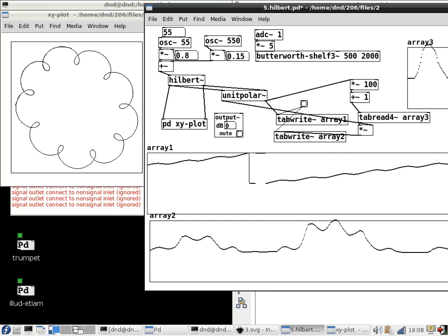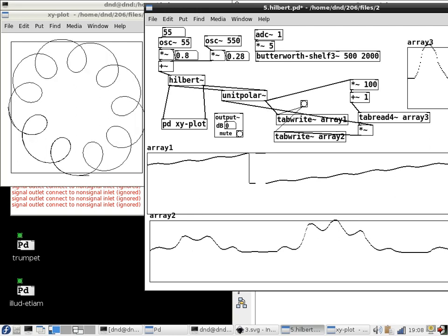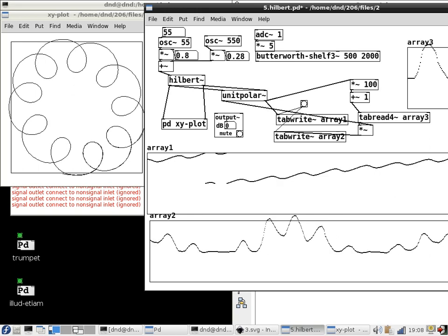But that's not going to matter because this table read, it doesn't because I didn't draw it well, but this thing, if it's an actual periodic function, will give you the same thing down here as it does up there anyway. And so this jump and these 2 other jumps don't matter. Those are inaudible when you've replaced it with a proper waveform. And now the amplitude of the other harmonic then becomes the amount of distortion that you get in this thing, which also becomes the amount of phase distortion you get in this signal.